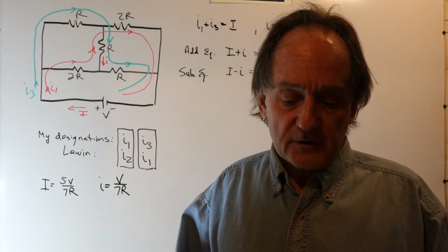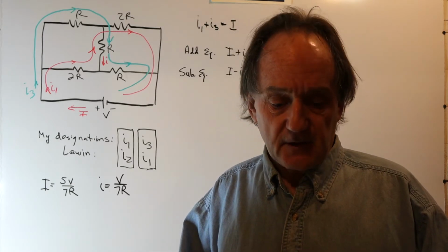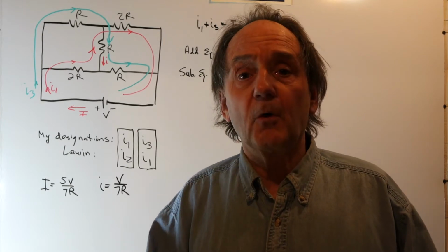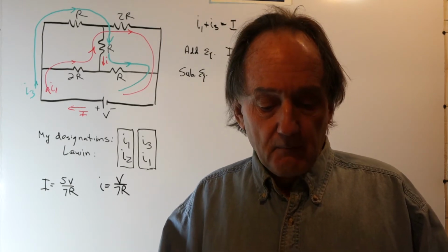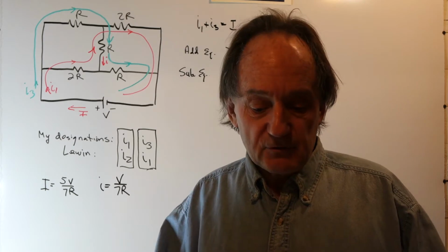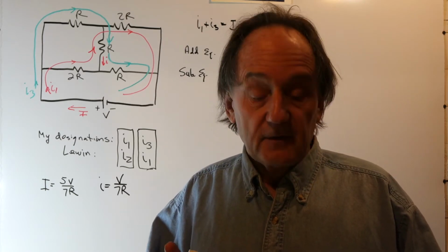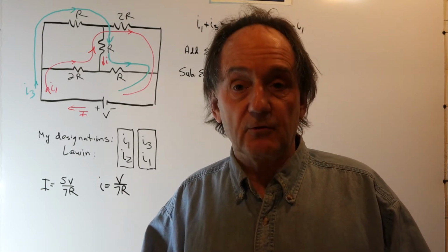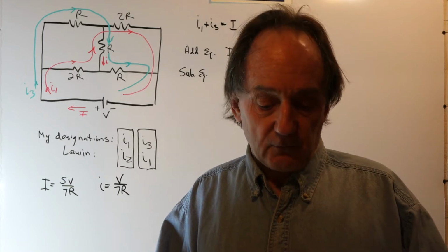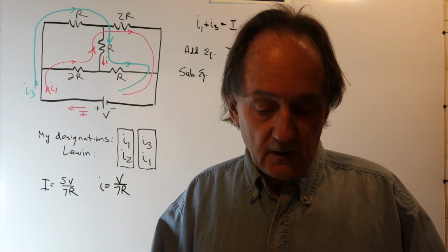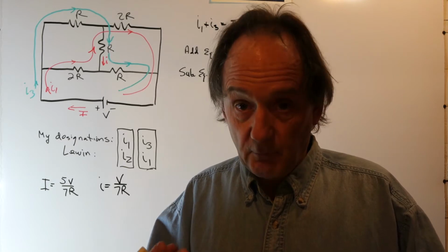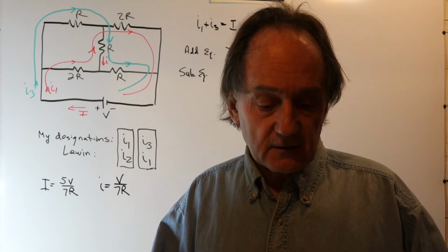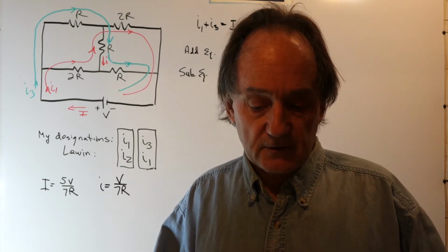Choosing two-loop currents is not an incorrect analysis technique. The method might not be completely general, like a formal mesh current analysis, but maybe a bit restrictive, but not wrong. The technique will not give you the true currents if the bridge is not symmetric, but it will alert you to that fact, which tells you to use a different method if you want the actual current values. In the R-2R case, it does tell you the currents are the correct ones.